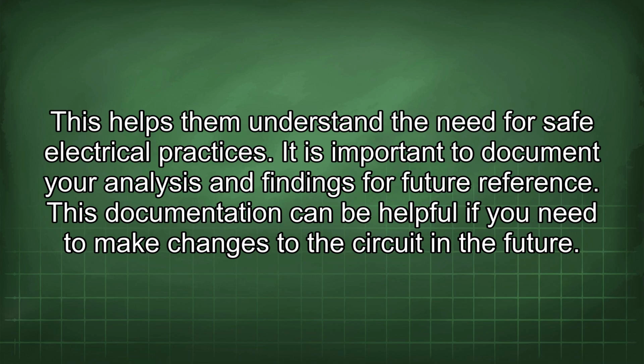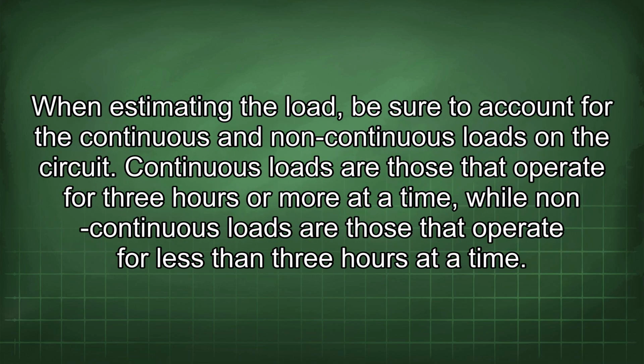It is important to document your analysis and findings for future reference. This documentation can be helpful if you need to make changes to the circuit in the future. When estimating the load, be sure to account for the continuous and non-continuous loads in the circuit. Continuous loads are those that operate for 3 hours or more at a time, while non-continuous loads are those that operate for less than 3 hours at a time.